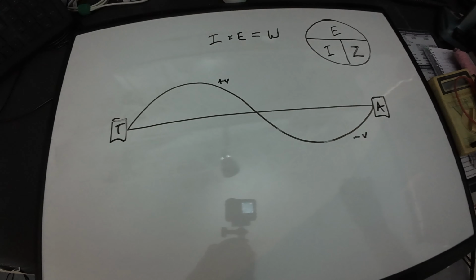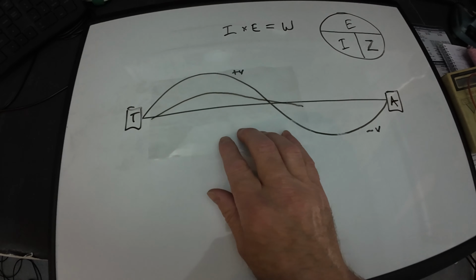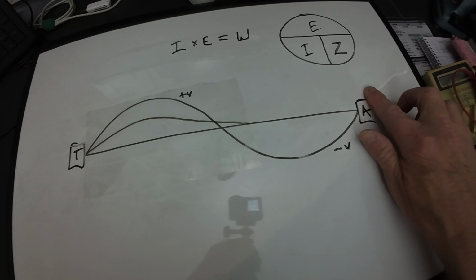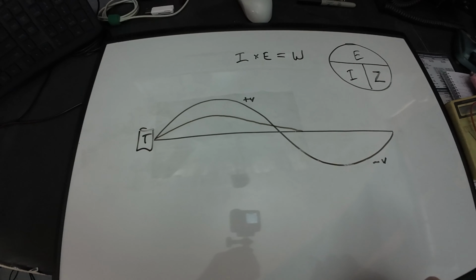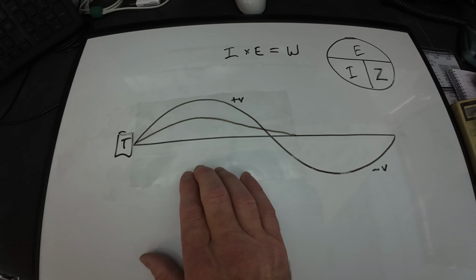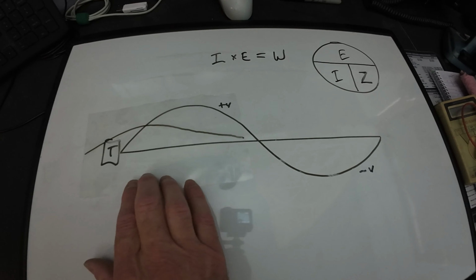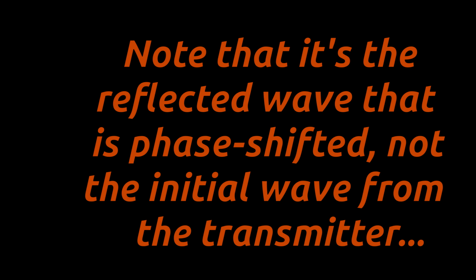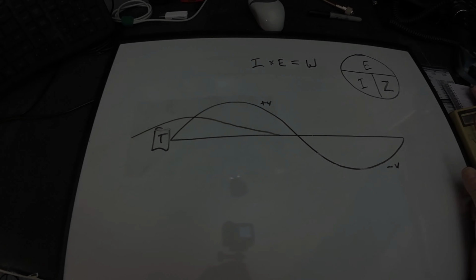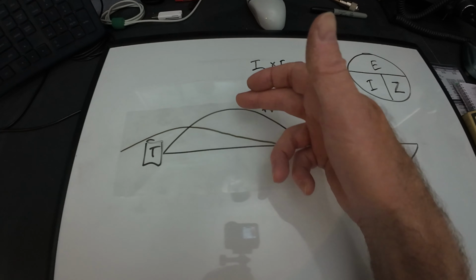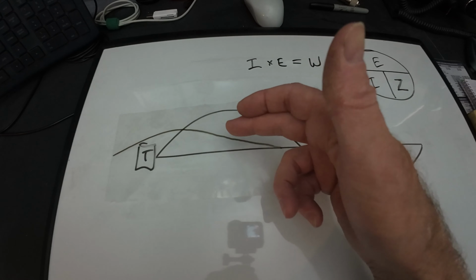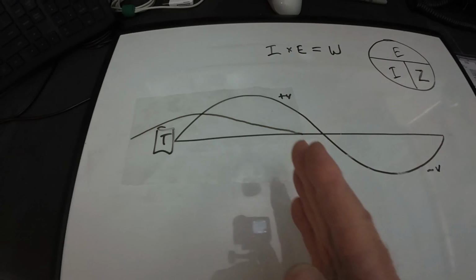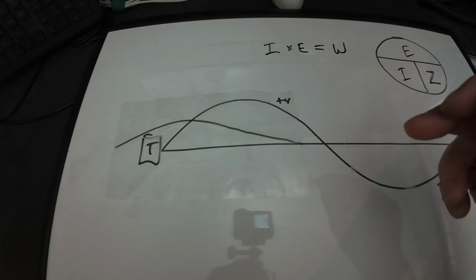So then what happens if we're out of phase? Well, let's say we have a purely capacitive circuit. We're going to take the antenna off of the end of this thing. Now we have a severe mismatch, and our current is going to be ahead of our voltage by 90 degrees. Now we've messed up that relationship. Obviously the impedance is going to change, because if we take our voltage, we divide by our current, we're going to get a Z that's completely different. And interestingly enough, as we advance down this line, it's going to change.